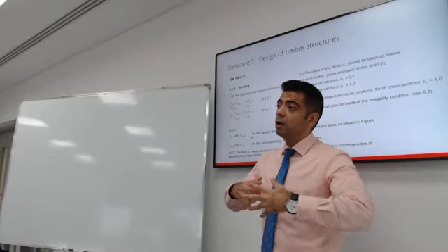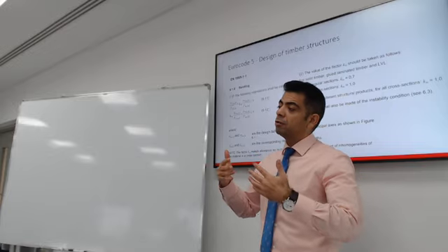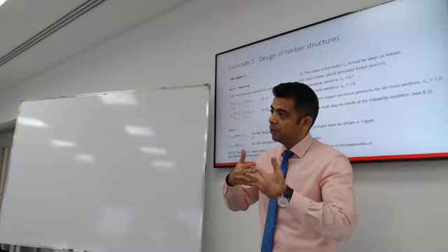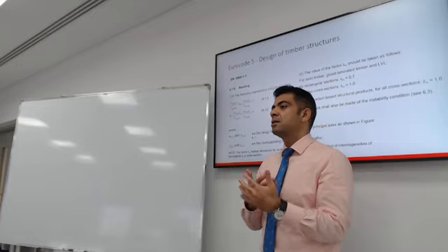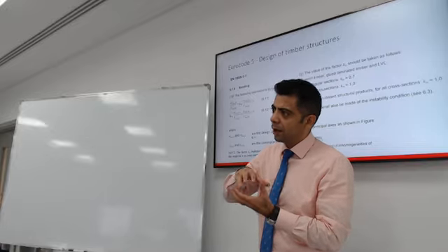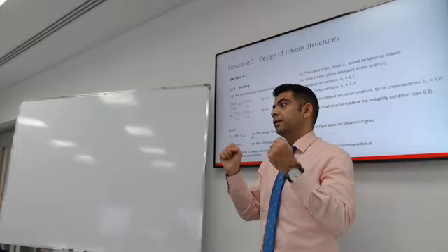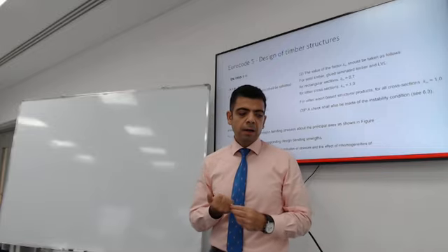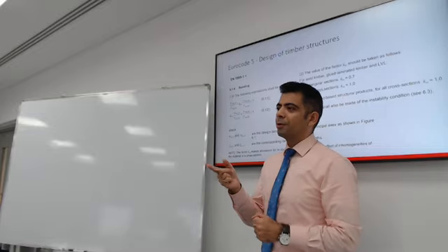So for wood, the stress-strain relationship is mostly linear. It will take load, then it breaks suddenly. Same thing with concrete. Concrete will take compression all the way to crushing, and then you'll have a violent, sudden, compressive failure. But you guys were on the right track.